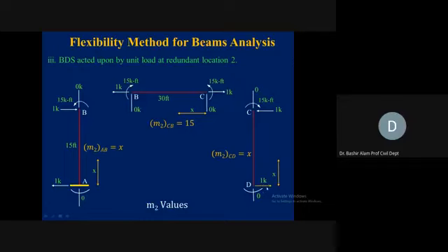Rightward directed, as AR2 was also rightward directed. Let's ignore all these member actions, and we start in another way now. We first find out the support reactions. We take that particular element, and then we analyze each and every member and joint. Now, to find the support reaction at A, this is the only support, which is a fixed support.